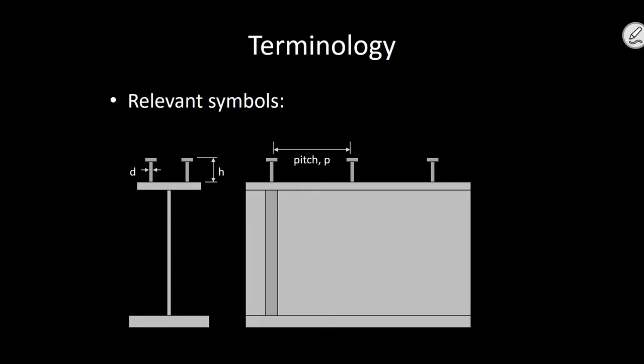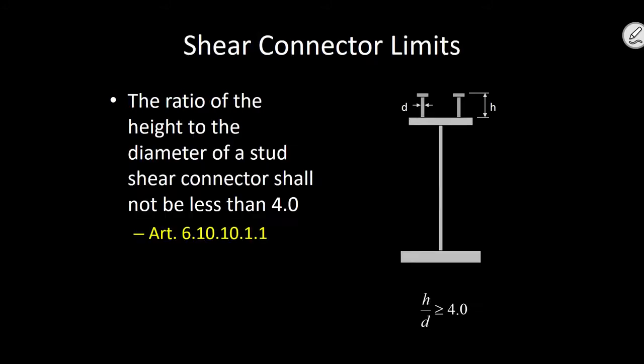Now, a little bit of terminology. So a stud has a certain diameter D and a height H, okay? What we're ultimately solving for in the world of stud design is the pitch, okay? In other words, we're trying to determine how far apart those studs need to be spaced along the girder. Make sense? Okay. Now, these are a couple of limits which are pretty basic. There's not really a whole lot that needs to be said. It's just trying to determine that the shear studs behave the way that we intend, that they're being effective, and that they penetrate far enough into the concrete deck.